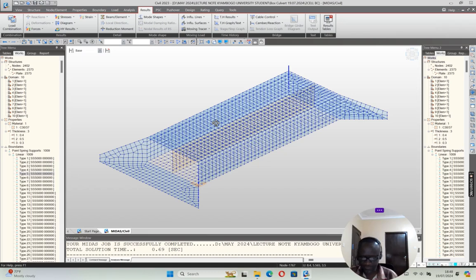Now if the lateral soil pressure is always generated, we use the at-rest coefficient, which is about 0.5 to 0.6. Let me adopt 0.5. Then we have our fill of 500, and our wall external top to bottom is 3.5. No, it is actually 4 meters. So you have a total of 4 meters plus 0.5, that is 4.5 meters.